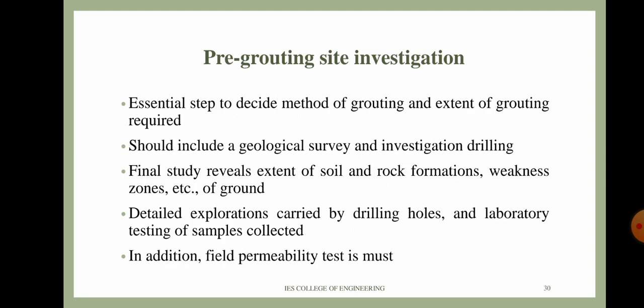Moving on with pre-grouting site investigation. It is essential to conduct a full site investigation before commencing grouting operation, so as to decide the method of grouting and the extent of grouting required in the particular selected location. The investigation should include a geological survey and investigation drilling. The study reveals the extent of soil and rock formation, zones of weakness, depth, strength, etc. of the ground.